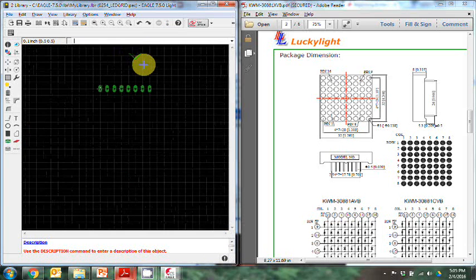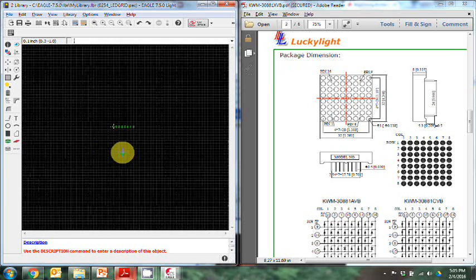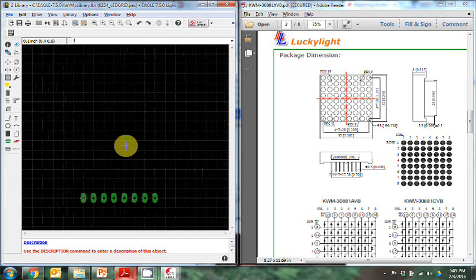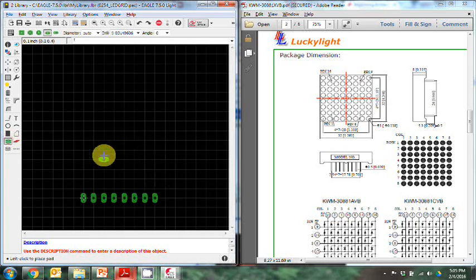Next I'm going to zoom out to make some room to put the other pads in. I'm going to start off by selecting the pad tool again, then counting up until I get far enough away. Remembering that my grid is set at 0.1 marks, I count up until I get to 1.1 inches, then I can start putting pads down from right to left instead of left to right so that they're in the same order. Remember, the pad numbers are incrementing all by themselves.